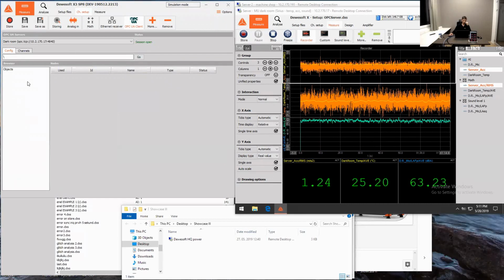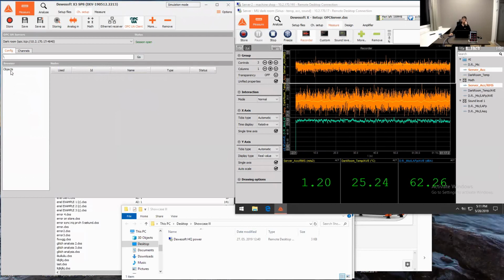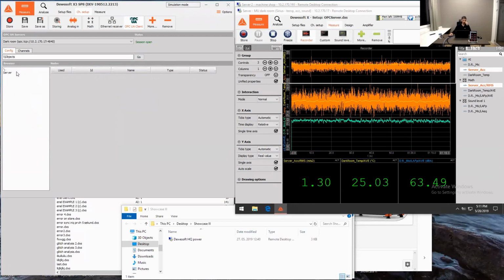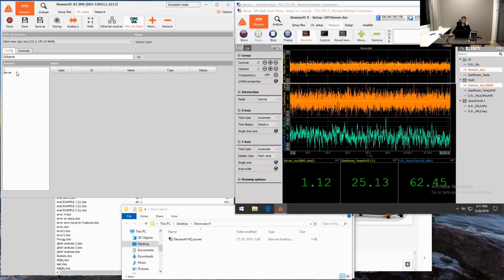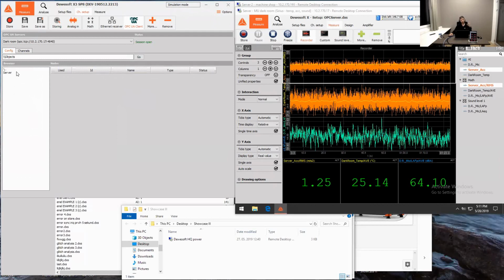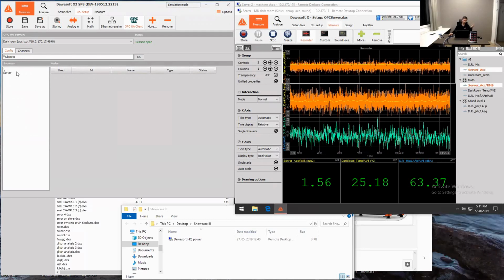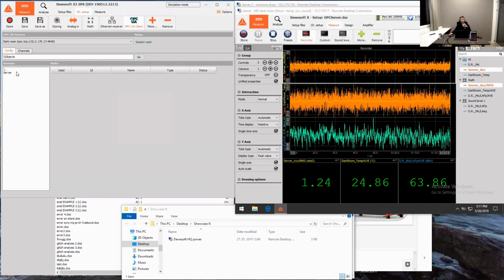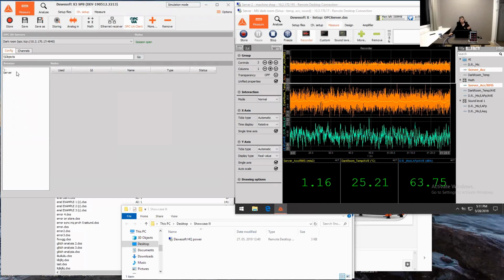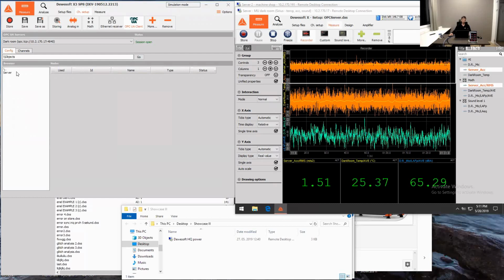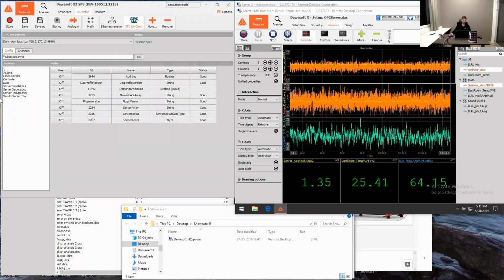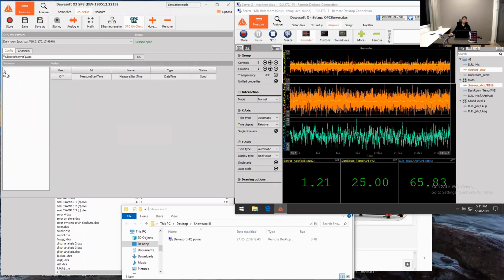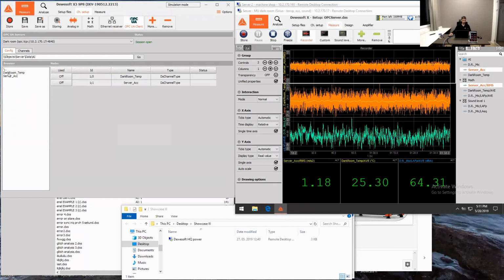From the browser on the left, there is the OPC UA information structure, which is a hierarchical structure, and it's quite easy to find certain channels or data sources. So we now enable channels one after another.